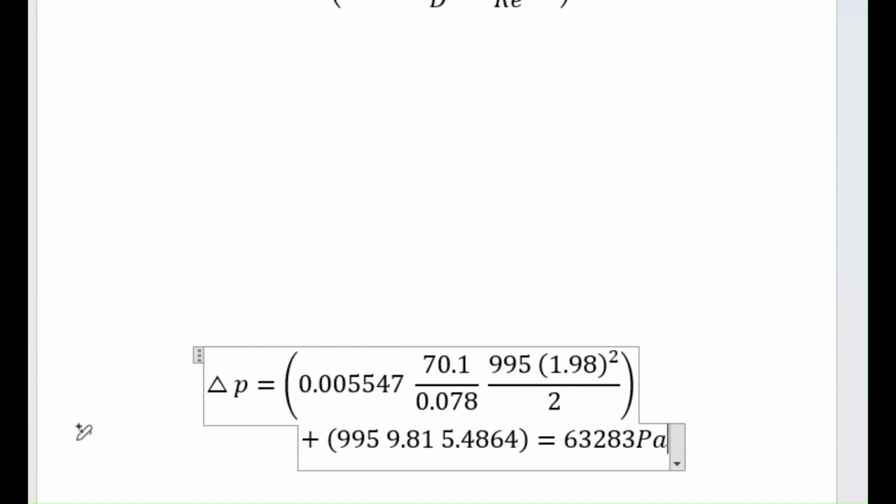If you're sizing the pipe, or let's say if you're sizing a pump, so you need to see the destination pressure. Let's say the destination pressure is 15 pounds. Okay, so to size the pump, you need the 15 pounds plus the 9 pounds pressure drop, plus additional, a design cushion for your deadhead pressure.